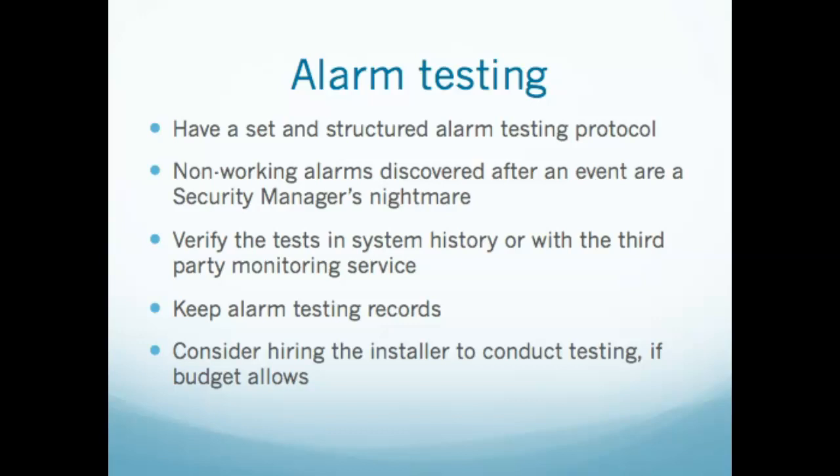You verify the tests in the system history, because when it reports either to the DMP or the host or to both, it will make a record of it. It'll be in the history right there with the card transactions that I went in and out of the room at this time. The alarm history also says the alarm tripped at this time and it reset at this time, every time it goes off. So you either check your own history to make sure it worked. If you're walking it all by yourself, you go test all the alarms and you go back to the host and look to make sure that they all came in.